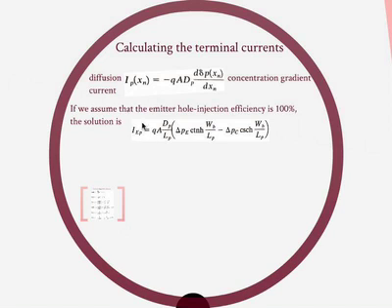We can relate the emitter current to the carrier concentration distributions. Okay? So the emitter hole current is now given by some expression here, which depends upon the excess carrier concentration at the interface of the emitter and the base, and the excess carrier concentration at the interface between the base and the collector. Okay? And this function is essentially a hyperbolic cotangent, hyperbolic cosecant.